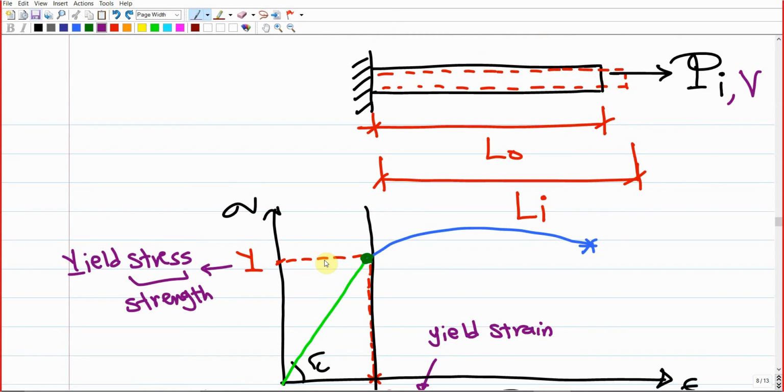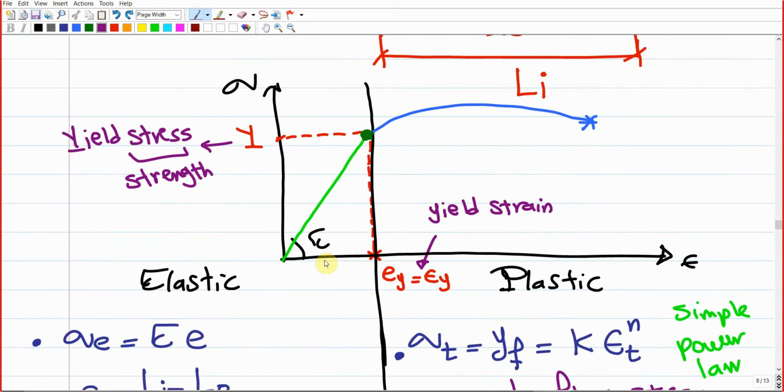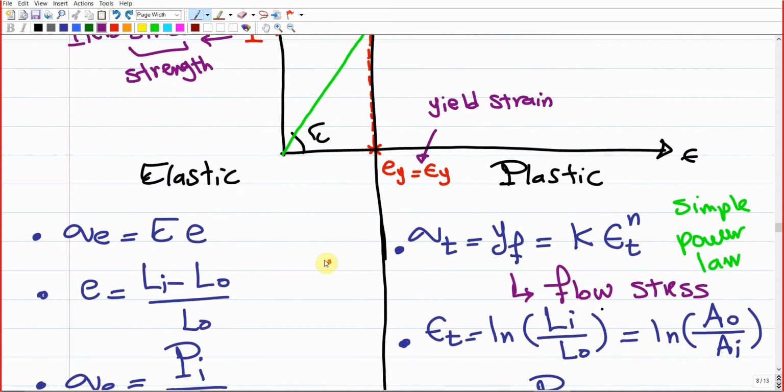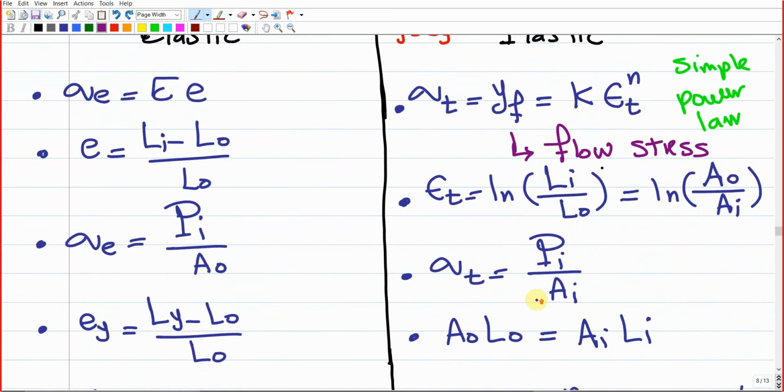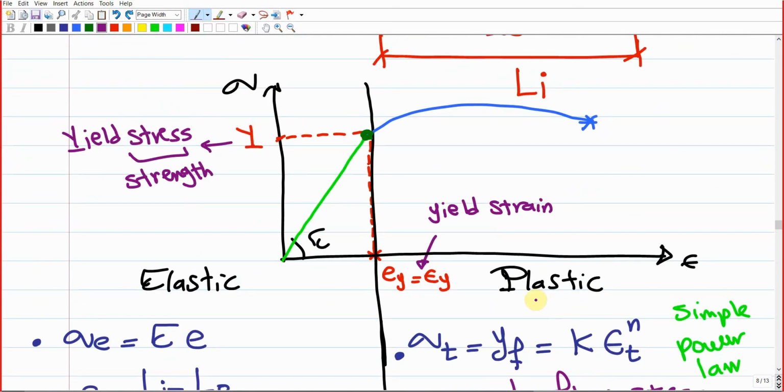So we're going to discuss these operations. Some of these operations, the way by which they change the material, depends on the flow stress. But some other operations depend on the average of the flow stress, something that we call the average flow stress. This is the thing that I'm going to discuss now. So for example, what is the average flow stress? If we are exposing the material to a stress level that is higher than the yield strength, we shall be moving to this point, for example. Assume that this is YF, the true stress at this instant.